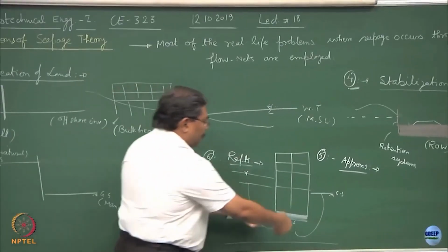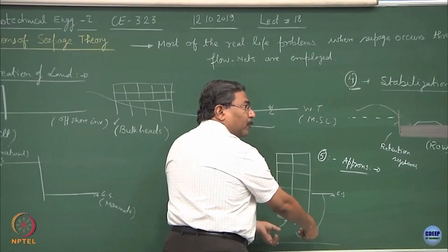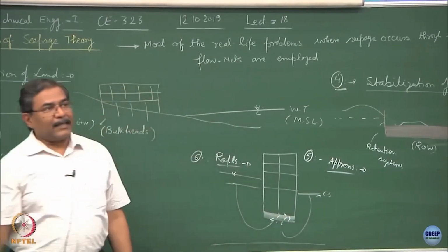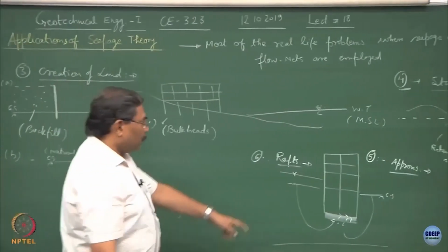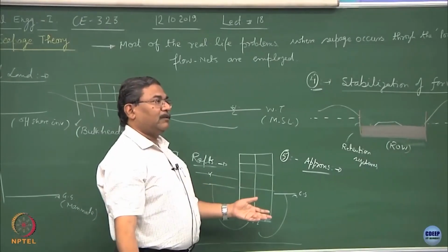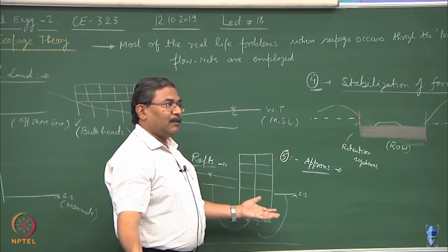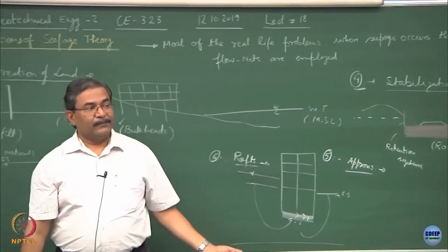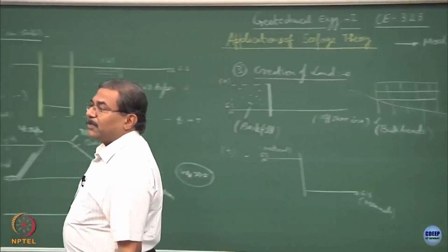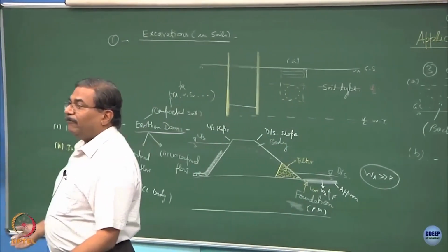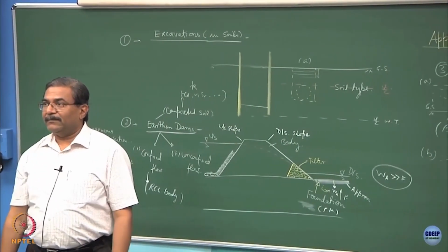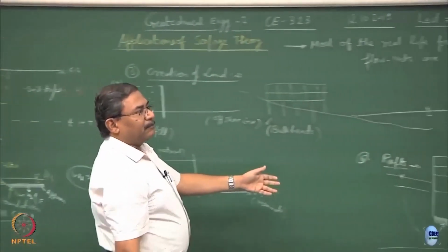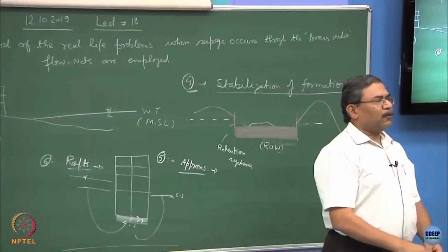And if this system is not strong enough to resist the seepage force, what is going to happen? This whole thing will crack. And the moment it cracks, the underground storage which you created is of no use. Got it? This is happening in most of the projects in the country right now. Crores of rupees are lost because of defunct properties. 3-4 cases I am doing right now where this is the main problem. But a good answer would be to anchor them,